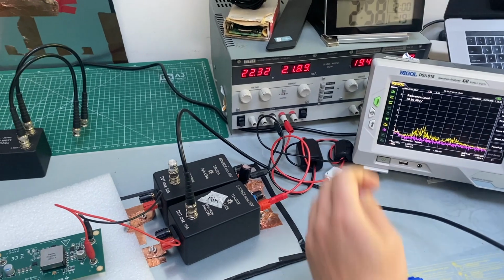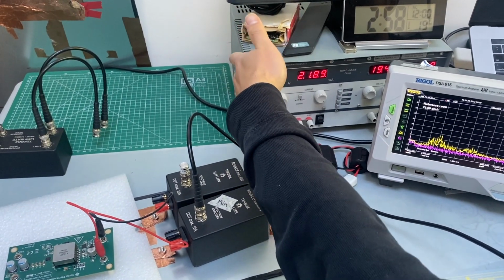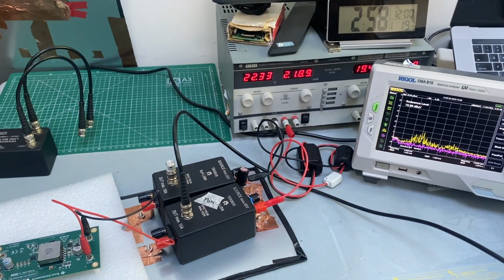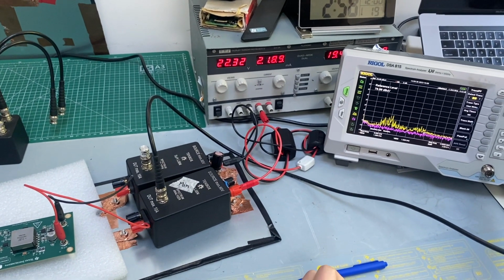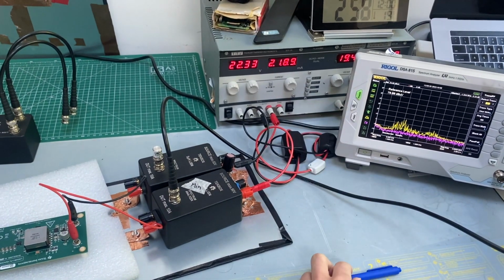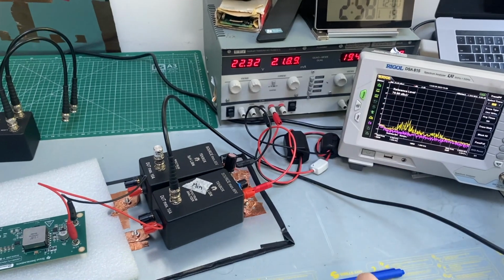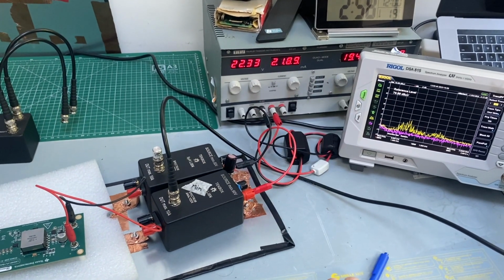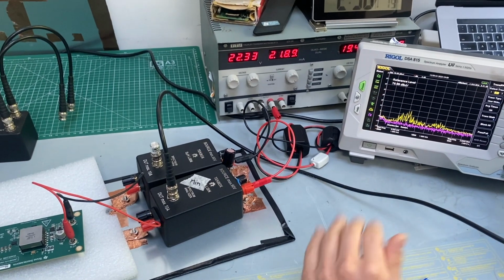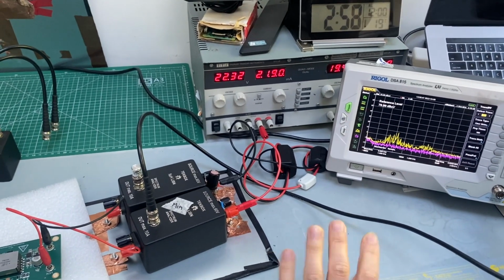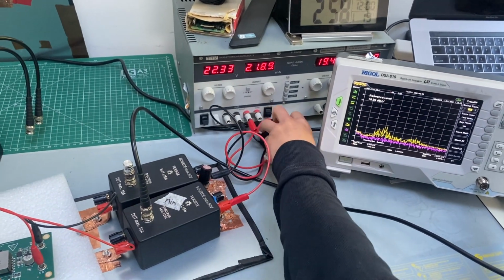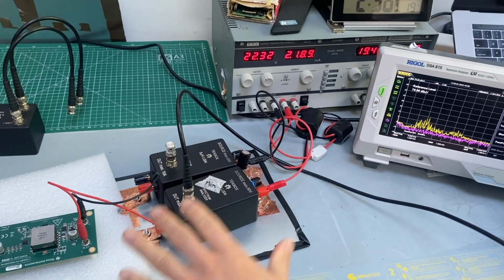Okay, so because sometimes these power supply units are most likely isolated power supply units, sometimes you do need to suppress the noise on the input and output side to make sure that the common mode noise is low enough. So that's a first tip in setting up the LISN: eliminate or suppress the ambient noise as much as you can. Now, with ambient noise low enough, we can move on to test the DUT using a LISN